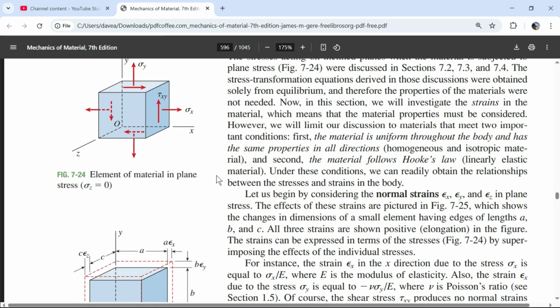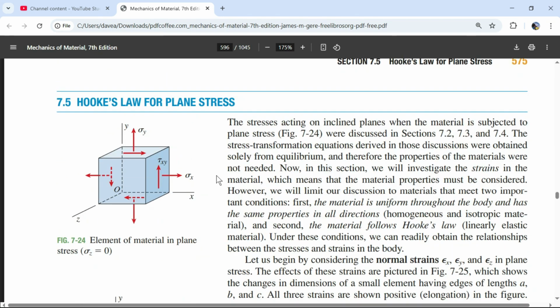And so because of that, when it gets down to materials, if I had a 1-inch bar of steel, I can pull 58,000 pounds in tension on it. But if I only had a half-inch bar, or a bar with a cross-sectional area of half an inch, like maybe it was 1 inch by half an inch, I could only pull in tension on that 29,000 pounds, or half. But the pressure on the surface is the same, still 58,000 psi in normal tensile stress, and that is going to be a failure point for steel.